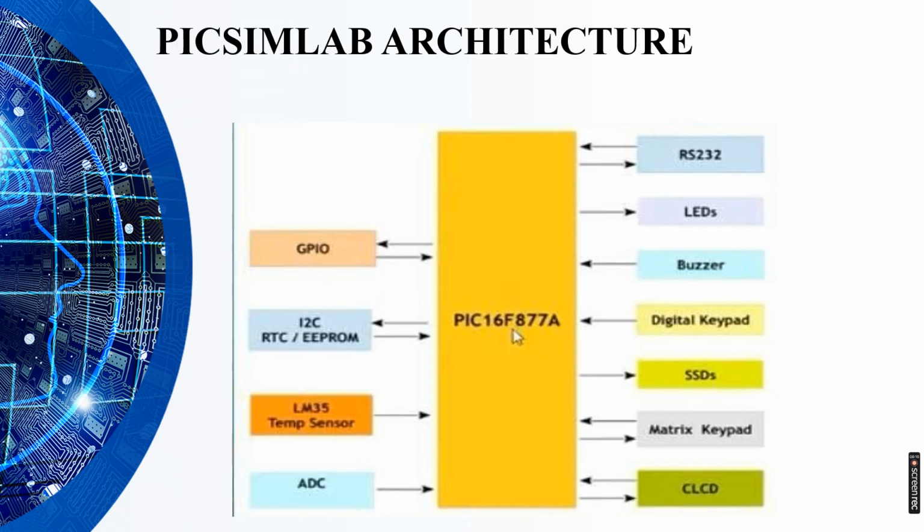See here what the PICSimLab architecture is. We have various components like GPIO, I2C and ADC on one side, where the temp sensor and ADC give input to PIC16F877A, and on the right side there are RS232, LEDs, buzzer, digital keypad, SSDs, matrix keypad, CLCD. Here we can see that PIC16F877A gives a single way output to LEDs and SSDs.